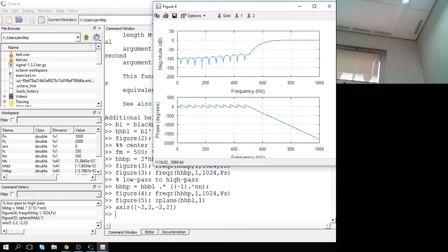If you really want to have the order number different, then basically you need to align the filters so that if the other one is wider, you add filter 1 and filter 2 so that you are adding those in the same place. So what you are adding? Well, you are adding the impulse responses in time space. Okay, so that's how you match different length FIR filters, for example, to make the band stop filter.